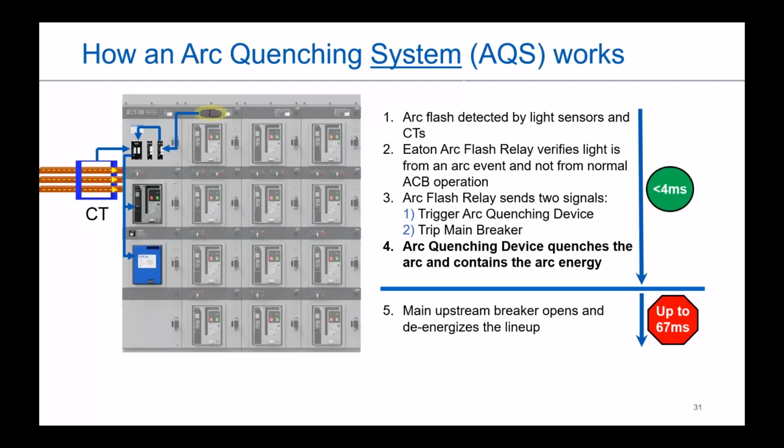And then the last question is, is there a specific arc flash relay that's recommended for use on the primary or the secondary of the transformer? It'll vary by manufacturer. For our system, we certainly have stuff that we recommend because that's what we build with. But I'm not going to try to do anything from a commercialization standpoint. There's a number of manufacturers out there. Most of them, I would say, operate fairly similarly, focused on anything internal to the piece of equipment they're installed in.